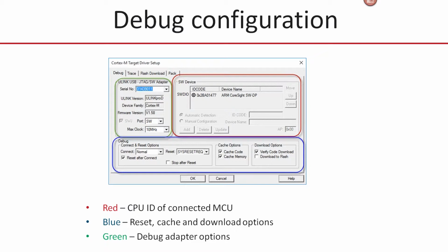Also, the Cortex processors, their startup on some of them is getting more complicated. There are on-chip bootloaders, etc. So down the bottom here, we have a selection of different connection methods, how to reset the processor through hardware reset line or internal reset registers. So this allows us to tailor how the debug adapter is controlling the Cortex processor at reset.